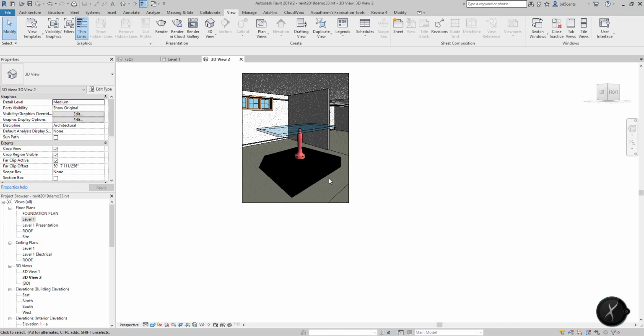You learned to create extrusions, revolutions, blends, lock geometry to reference planes, and flex the model to check to see if your parameters work. So what we're going to do is we're not going to save this yet. We're going to continue on, with material as a parameter within the family.